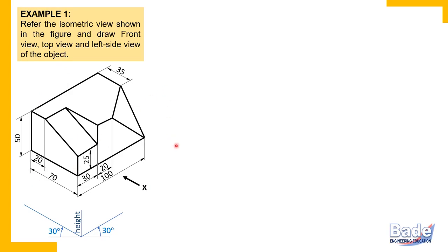With reference to the length, width and height axes, we can define 6 sides of the object: front side, back side, left side, right side and top side, bottom side. In this case, the front side is always denoted using such an arrow. What does this arrow suggest? The front side of the object. When an observer watches this object in this direction, he gets the front view of the object. So this is the front direction, or the front side of the object.